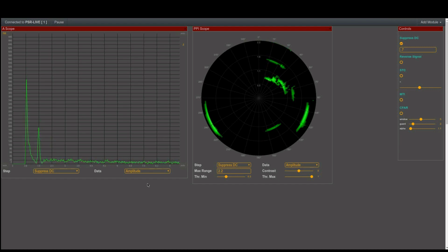Now let's move over to the threshold in the A-scope. We didn't do much there. It's set to 10 meters. We set some threshold, top, and on minimum. So you see the clean signals because we've got no noise anymore, illustrated by the red dotted line, where we see where we set the threshold.